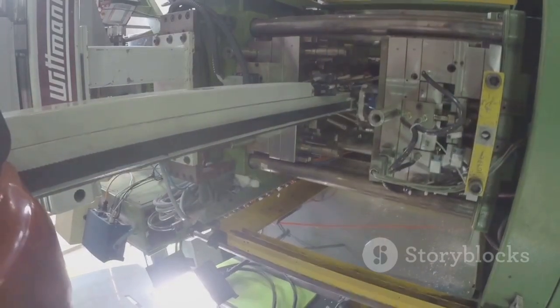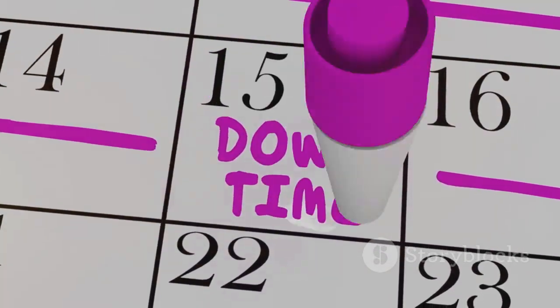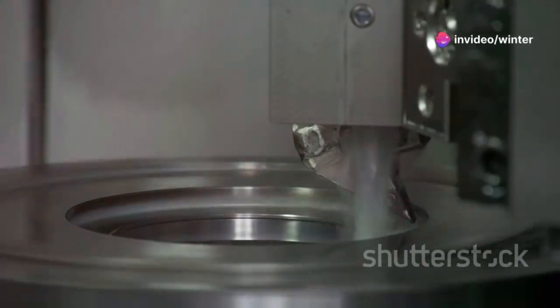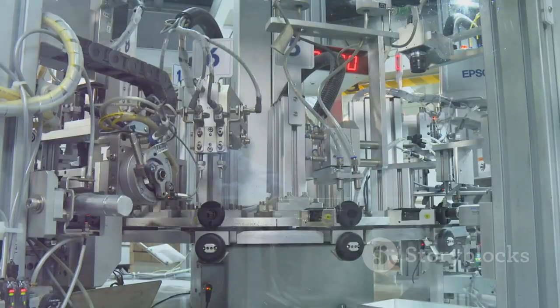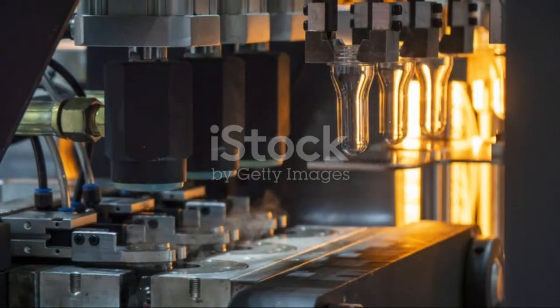Standardization speeds up production and maintenance. When a standard pin breaks, you're back up in a day. Custom parts mean long delays. Build your mold around what's readily available. Save money, reduce lead times, and make maintenance easy. Standardize wherever you can. It's a simple step with huge payoffs. Don't reinvent what already works.